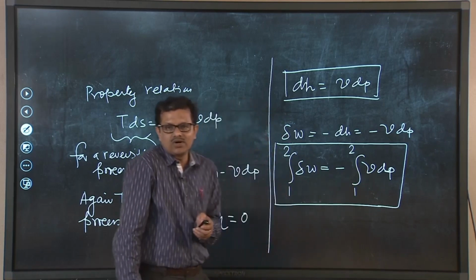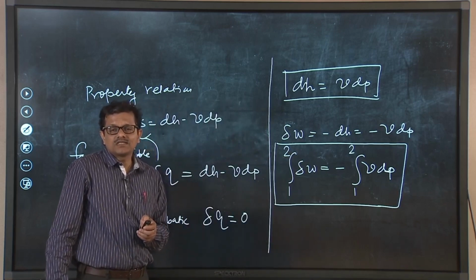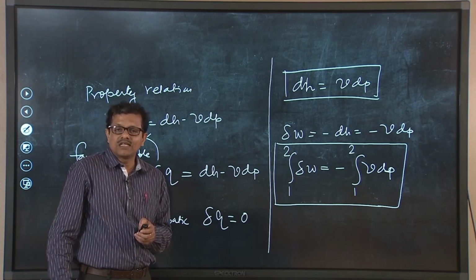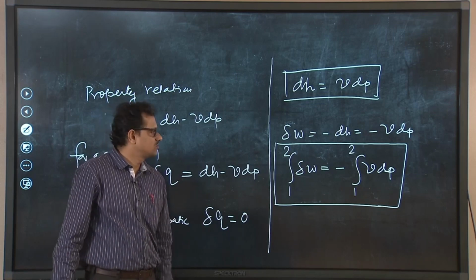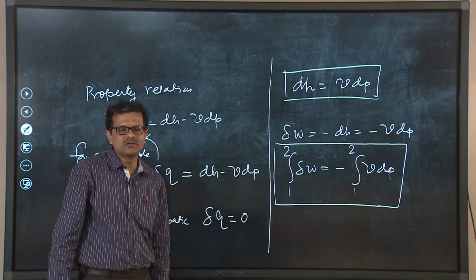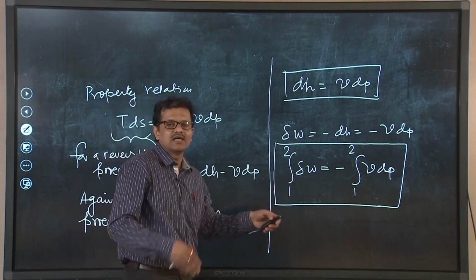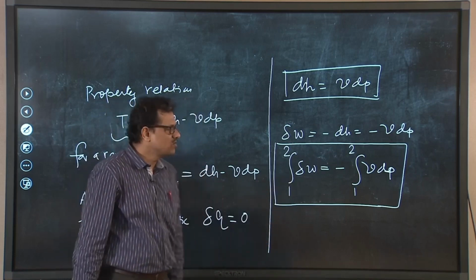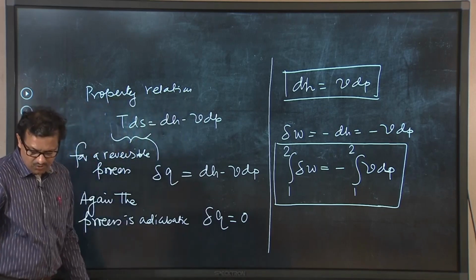As I said, in the compression process the objective is to raise the pressure with an appreciable change in density as well. So, specific volume also will change. So, knowing the specific volume at state points 1 and 2, we can calculate what would be the work done, and that amount would be consumed by the compressor from the turbine work output.